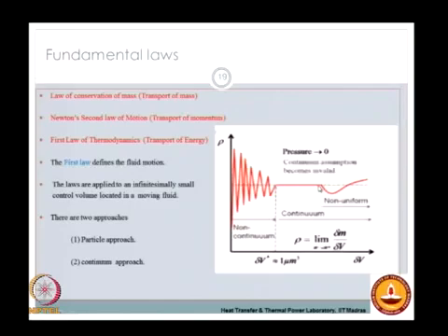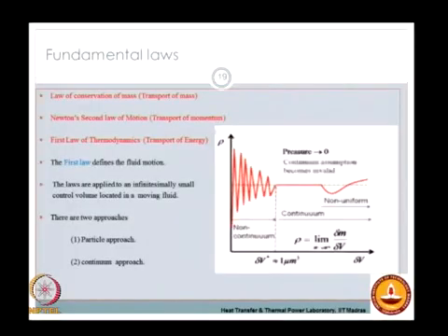So this signals that we have moved from a non-continuum regime, where you have very few particles or a very small control volume and could not statistically define an average property such as density, where the particle approach could be used. For volumes greater than this critical volume, the definition of density carries meaning, and the density becomes constant. Therefore the continuum assumption is definitely valid, so we will restrict all our derivations to a control volume satisfying the continuum approach.